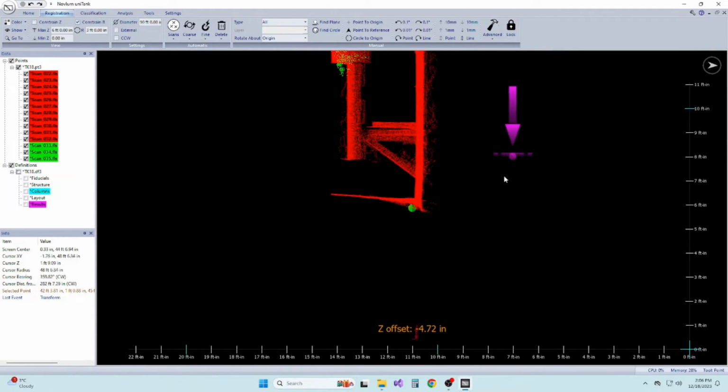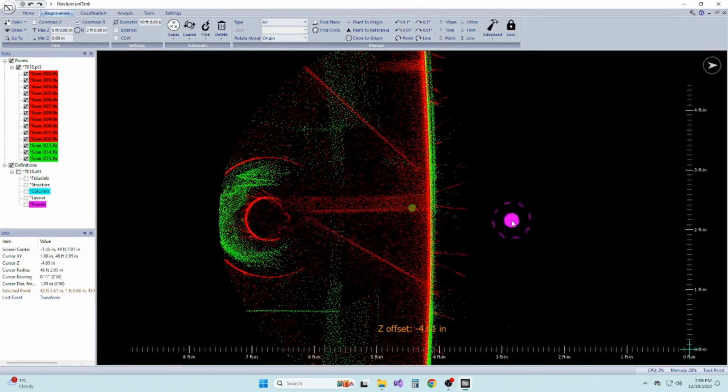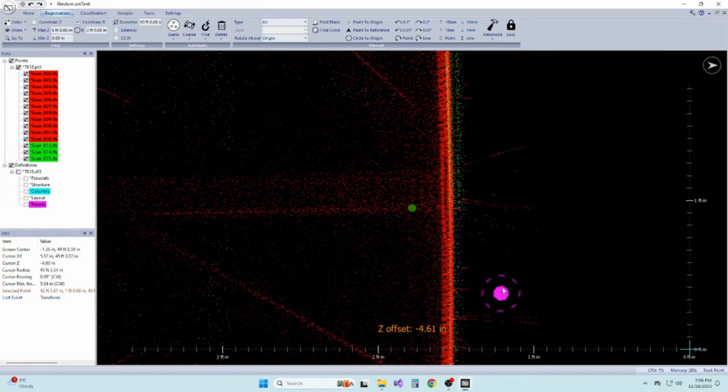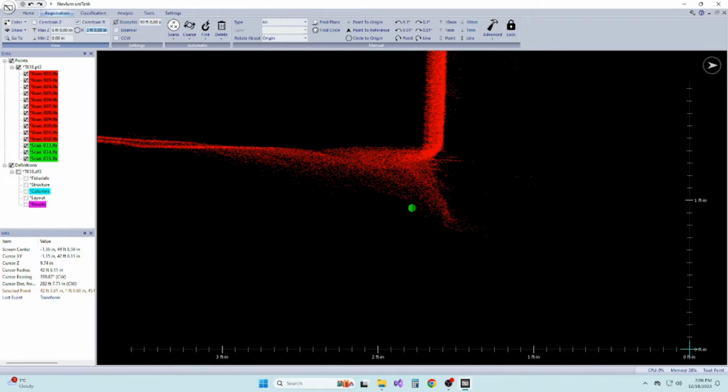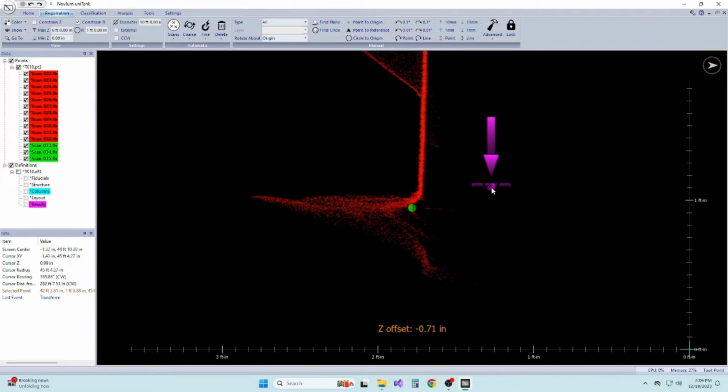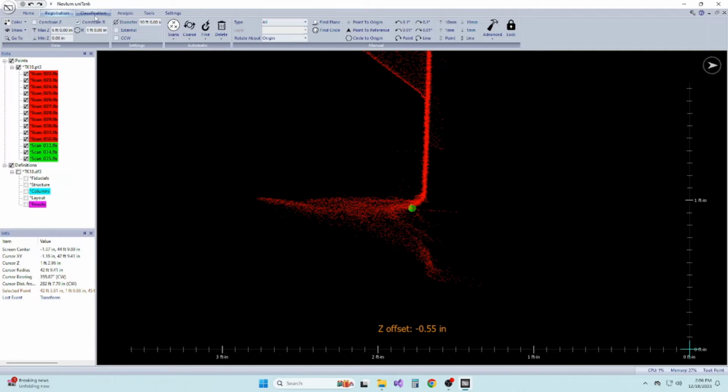With this new reference, we need to make sure that the bottom shell weld closest to it is set to 0. This is a very important step for capacity calculations, and you will get an error from uniTank if it's not set properly. Because most measurements we get from the field, such as course heights, overflow heights, max fill heights, and floating roof heights, are physical elevations and not liquid level.